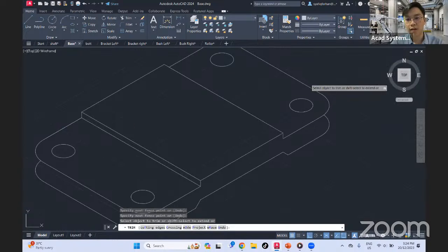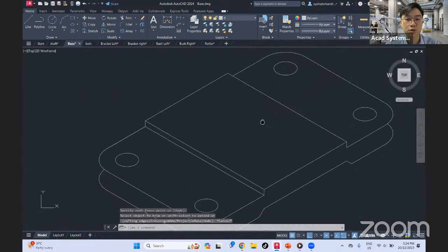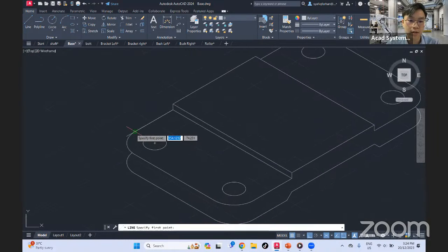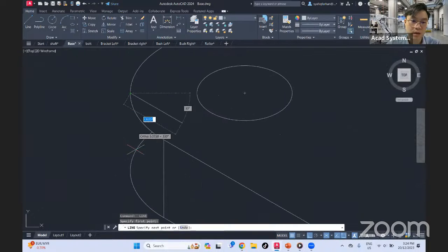So when you have deleted all the extra lines, all your construction lines that are not supposed to be there after fillet, you can go back into line and draw one straight line down from the end point of the arc of your fillet, and snap onto the next endpoint, the bottom endpoint. So this is to show or demonstrate that it is actually a fillet. And often over here on the corner, I'll select the quadrant and snap onto the next quadrant.